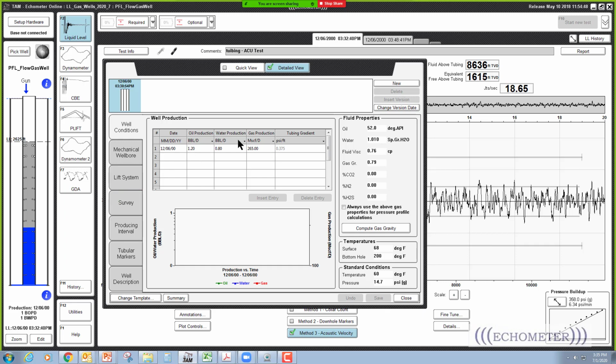And we draw that based on the well test. So anytime you shoot a fluid level down the tubing on a gas well, we're going to show the fluid in the tubing divided based on the fluid volumes from the test. And you'll have needed to type in the oil API gravity and the water gravity to get the weight of this fluid calculated properly.